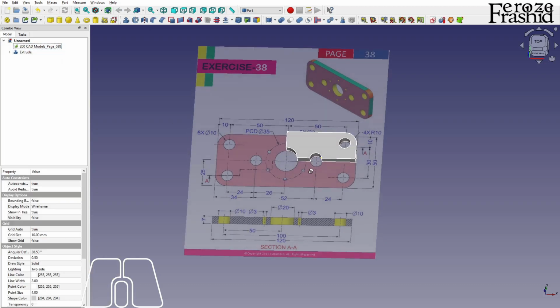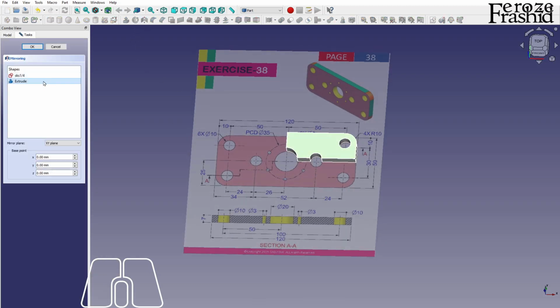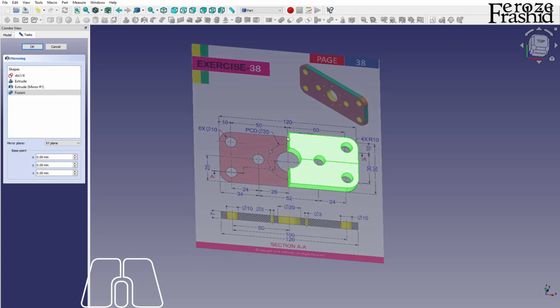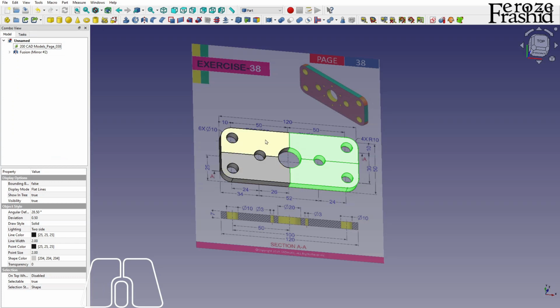All right. And now I want to make a mirror on XZ plane. Take these two, make a union, and take that mirror part and mirror it against this plane, which is YZ. Right? And take these two, make a union. So this is our object without holes. Well, it's got some hole, but we need to work on a few more holes as well.